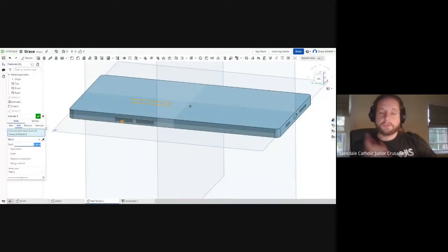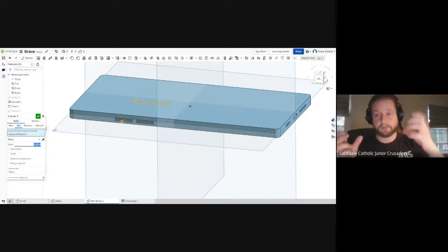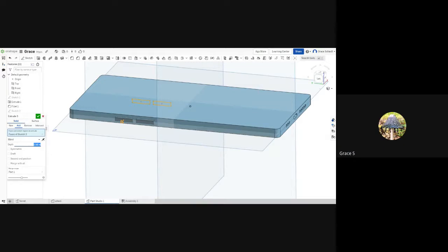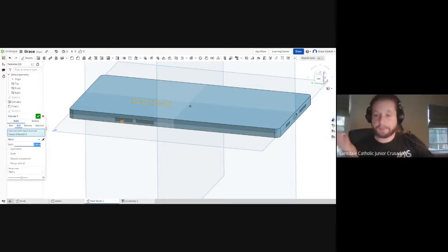So if you extrude from the center and you just use a blind extrude like you did, what you might run into is, let's say the phone got wider. What happens when the phone gets wider when it's modeled as you have it? The extrude isn't really going to be there. Yep, the buttons will basically be subtracted into the phone. They'll just disappear because the phone got wider.